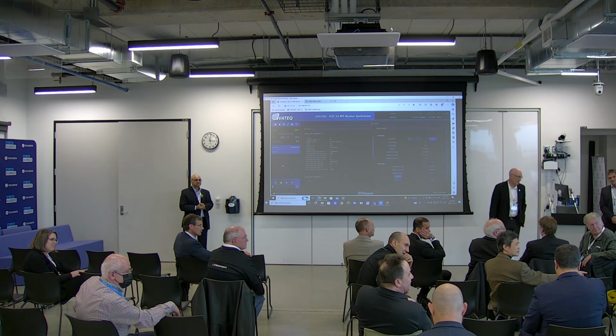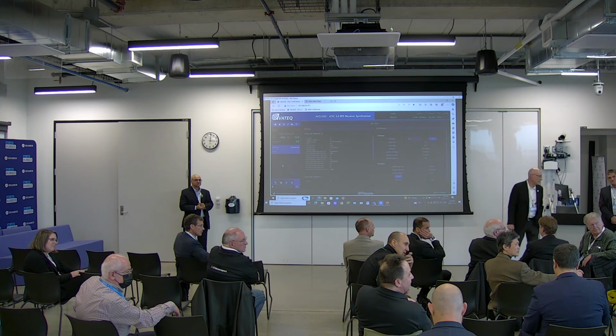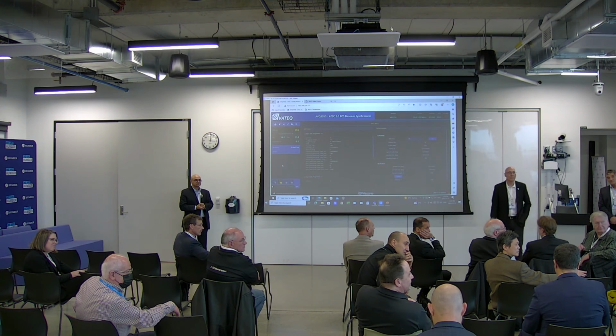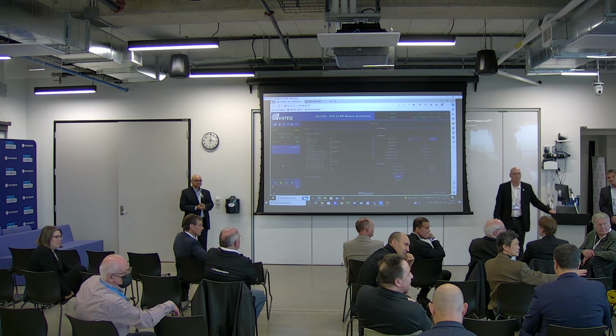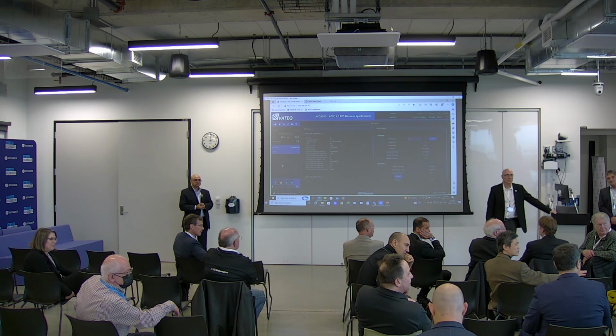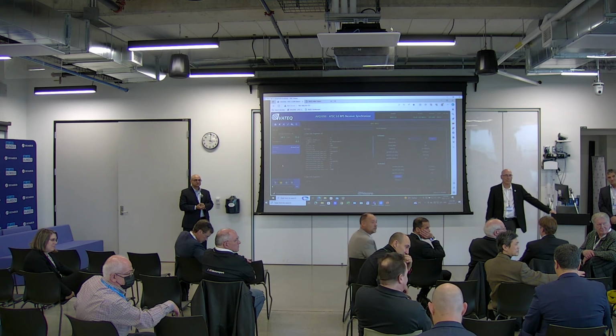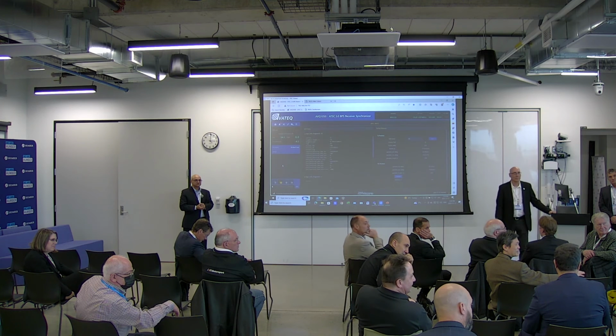That's high quality. So when we talk about precise positioning in GNSS or just in positioning and navigation, we're talking about a couple centimeters. So we haven't talked about meter, or we don't use meter. We haven't used that for a long time. I know that for the majority of the world, that's what they're looking at, but we don't look at it that way. And big part of the reason is the corner cases.